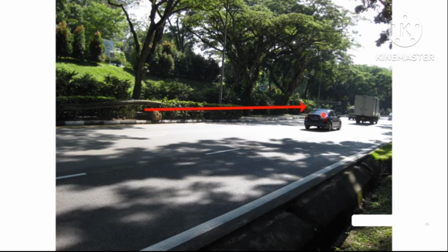from the accident site. The failure of these composites is not of ductile type, but it has huge amount of toughness due to the different failure mechanism of composite materials than that of the ductile materials. The broken pieces appear to be made of hybrid carbon and glass fiber with epoxy as the matrix. These pieces break in a very characteristic brittle type of fracture. However, before they fracture, they absorb much of the energy and therefore they are very tough materials.